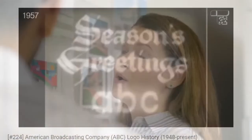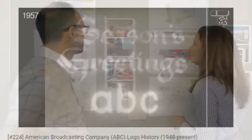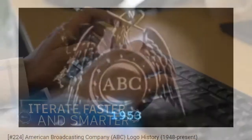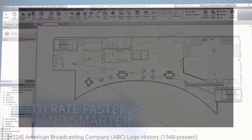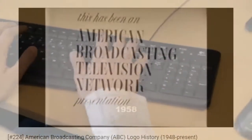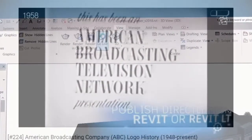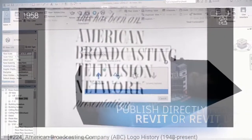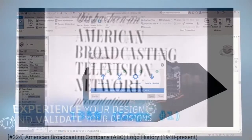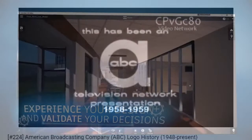All right, you are now in the Family Editing mode. And the ribbon will have different tabs and panels. Click the Create tab and select Void Forms from the Forms panel. Click the Pick Path tool from the Sweep panel. So we're going to do a Void Sweep. Pick Path from the Sweeps panel.